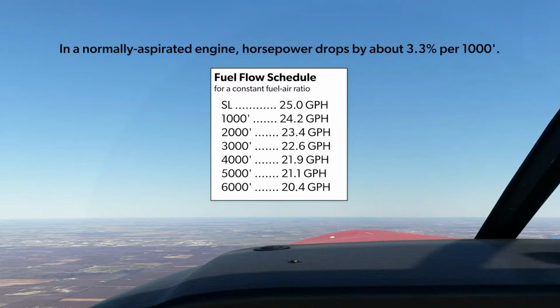And so if you had a 180 horsepower O-360, you should be seeing about 18 gallons per hour when it's making 180 horsepower. Anything above 200 horsepower, the rule is to divide by 11. So it's a little bit less than that, but this 250 horsepower Comanche comes with a 25 gallon per hour marking on the fuel flow gauge for sea level fuel flow.